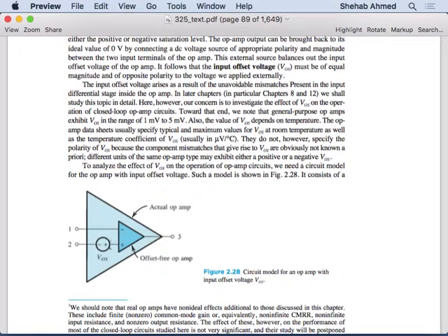The real op-amp will have an offset voltage. If this offset voltage is present and you short the terminals, your output will still saturate, because the difference between the ideal op-amp's terminals exists. There's a DC value there, right? What does the offset voltage do? It's like a voltage that is added to your non-inverting terminal voltage.